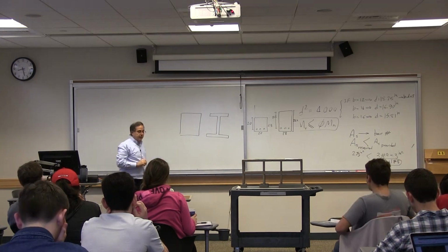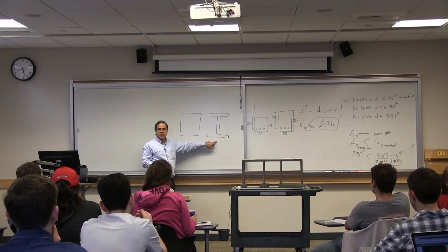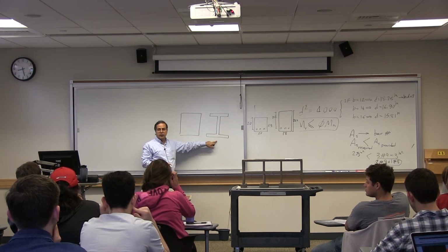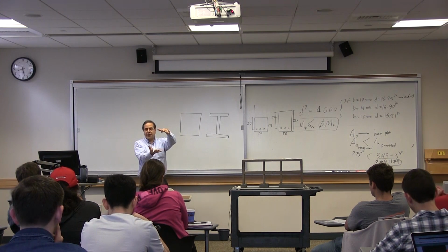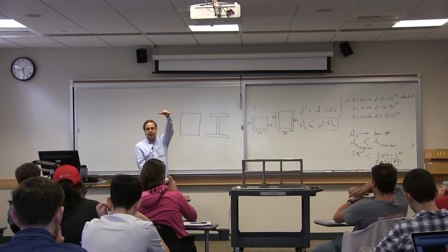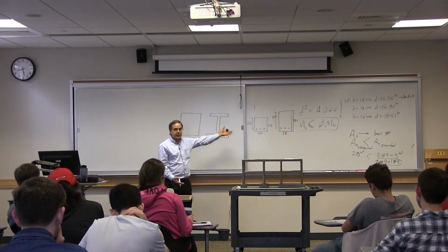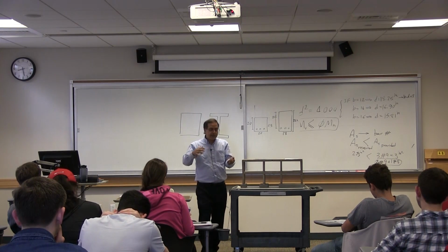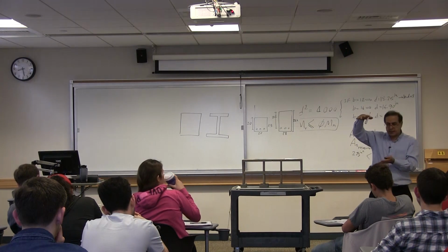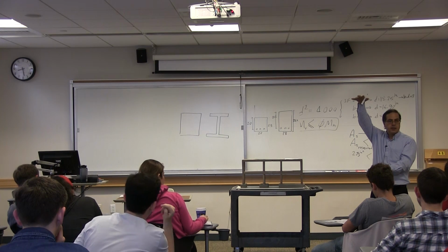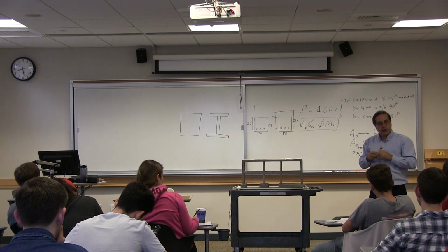When you make a steel section, do you use this geometry or this geometry? Why? Same reason. You want more material farther away, as far as you can. The same concept is here. What you want is the distance between the tensile and compressive forces as large as possible. So the larger it becomes, the more economically you are designing.